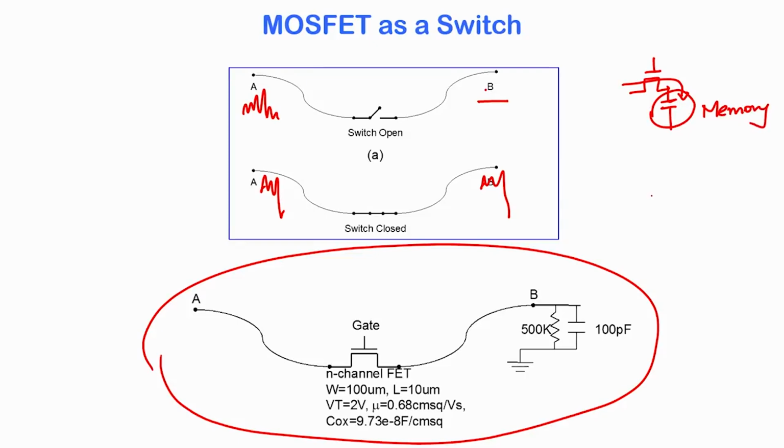The other applications are your circuits and displays or any active matrix systems, wherein you have a MOSFET and you have a capacitor again, and you store, and then you have a light emitting material. So, for example, say an LCD, and you store information on this capacitor and you open this MOSFET and you have the voltage here driving the LCD, so that you can see the color, the different levels of brightness on your display screen.